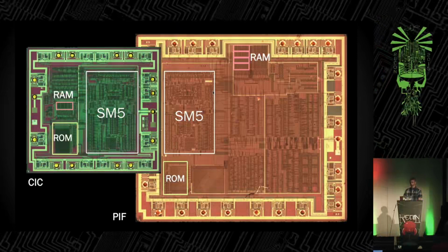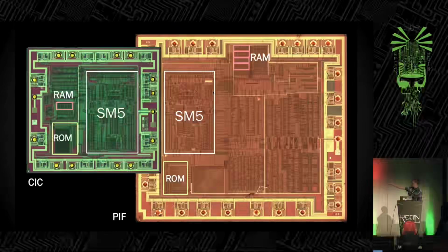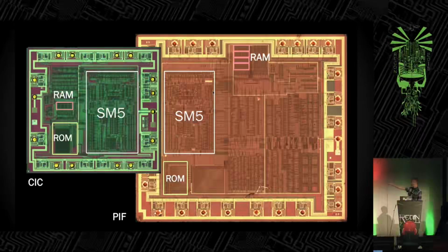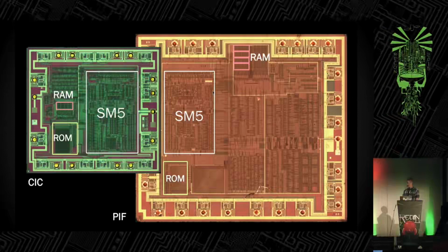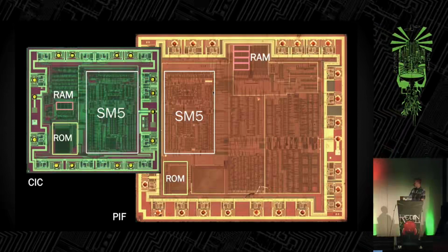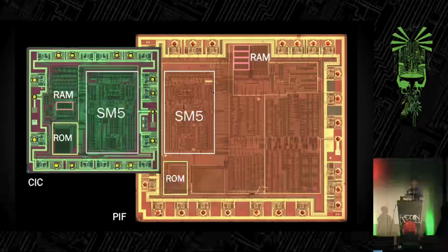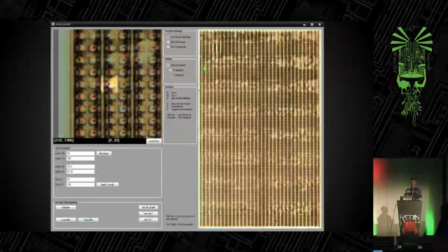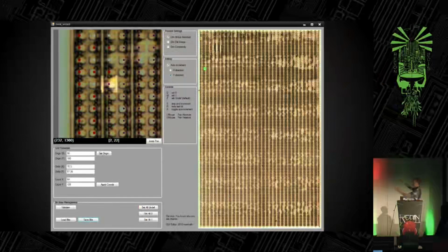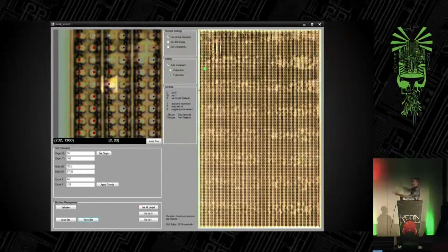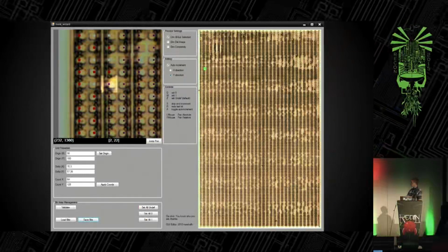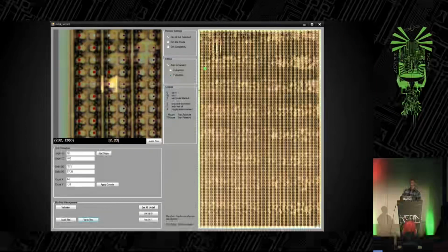So, like I said, we have this down in the lower left. That's the ROM image. That is actually the code that it executes. So using John McMaster's dash etch process, we could figure out what it looked like and then get an image. Once we had the image, which is that big thing on the right, that's the entire mask ROM. It's 8 kilobits, 1 kilobyte of data. Not exactly the hugest thing. It doesn't need to be.